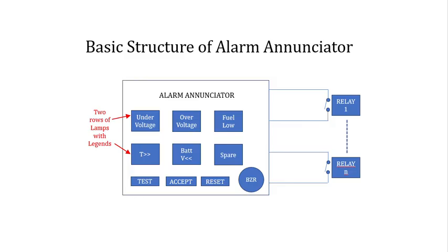One relay trips when supply voltage exceeds upper limit, and the other trips when voltage falls below the lower limit. For some machine, it is the air pressure or fuel level or lubricating oil level or battery voltage limits, etc. that trip relays. There may be a combination of many such machines, each giving indication by operating relay contacts.